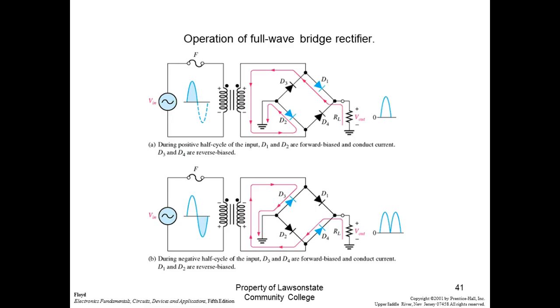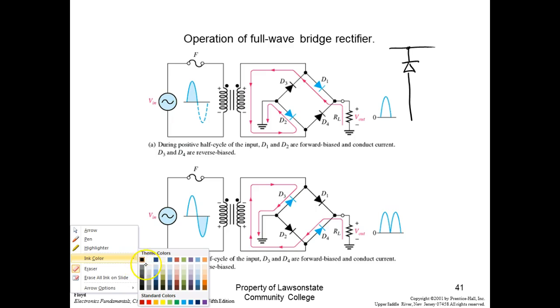So notice the way this is drawn. By the way, this is one way we can draw it, but the problem is this gets hard to draw and figure out the way the diode goes. Normally I'll draw it like this. What I'll do here is point all my diodes in the same direction and put a wire all the way through. And this is exactly the same circuit.